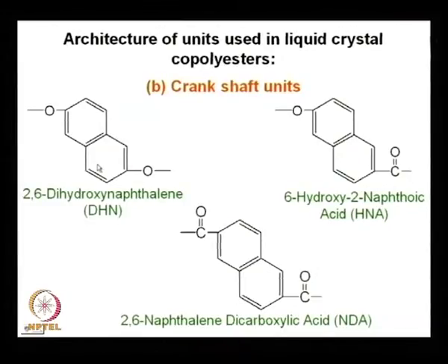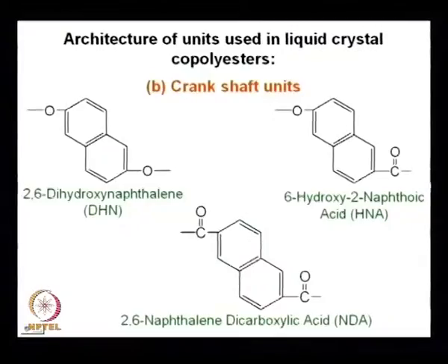It actually disturbs, affects molecular symmetry. So, if you have molecules containing that 1,4 linkage, para-para linkage, there you will have maximum symmetry, higher viscosity or higher melting temperature. If it is causing certain problems in processing, then you can incorporate such units in a few places. So, the melting point will be decreased, you will see later.